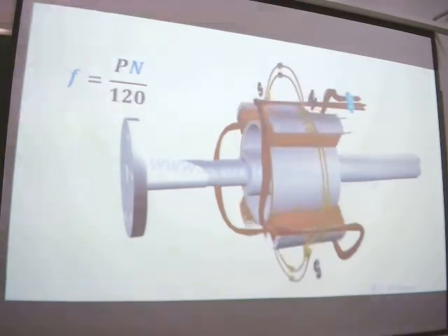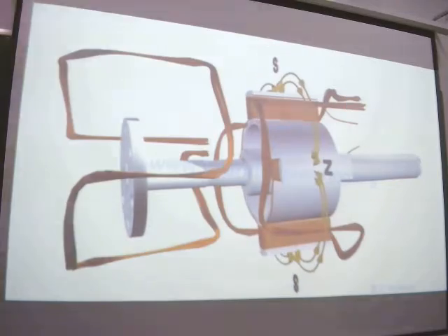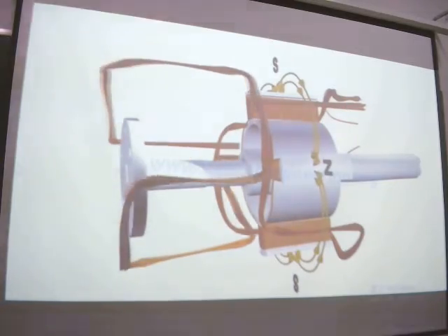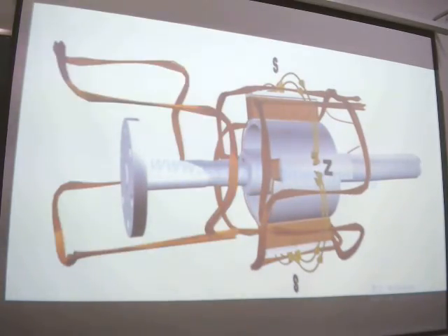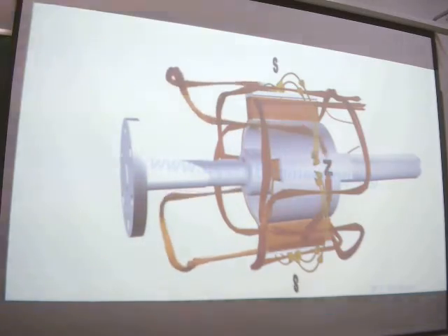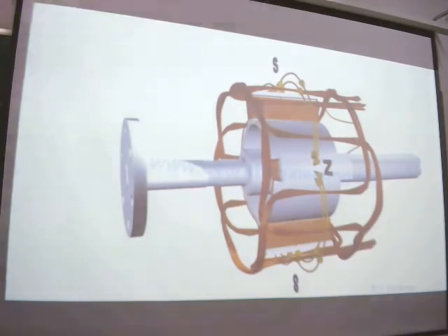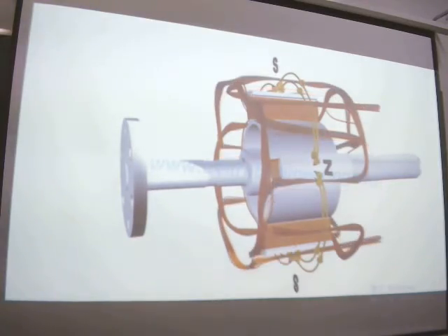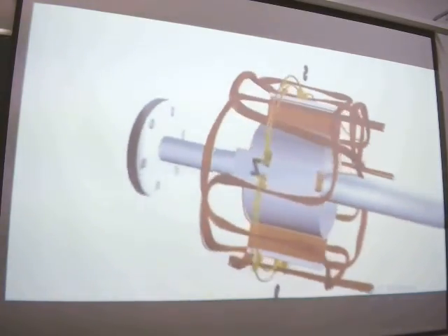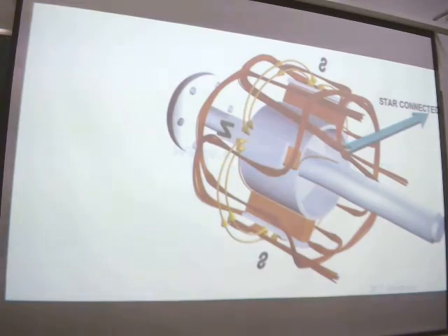For producing 3-phase AC current, 2 more such armature coils, which are in 120-degree phase difference with the first, are put in the stator winding. Generally, one end of these 3 coils are star connected, and 3-phase electricity is drawn from the other ends.